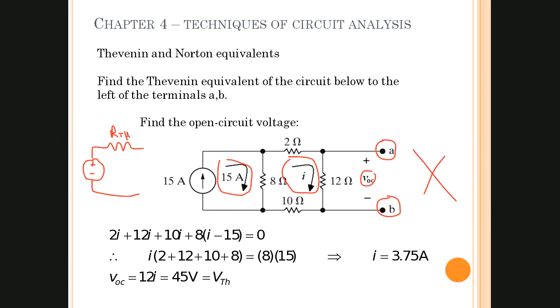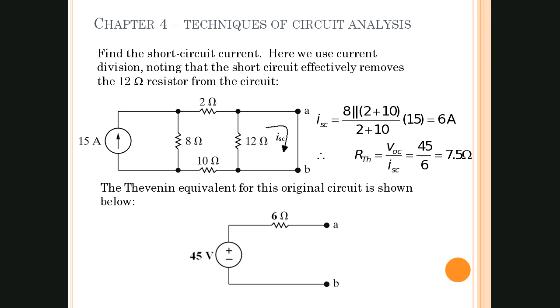Now again, this is a very simple circuit. Now here's another way of doing this. And again, when we're looking at something with just a few elements, it may not seem like that big of a deal between going from the regular mesh analysis or using something like Thevenin's equivalent, because there aren't that many extra steps in either one. But imagine that this is a much larger circuit, and the more complicated the circuit gets, you're going to see that using Thevenin equivalent and Norton equivalents, using what's called source transformation techniques, will help you simplify that circuit very, very quickly.